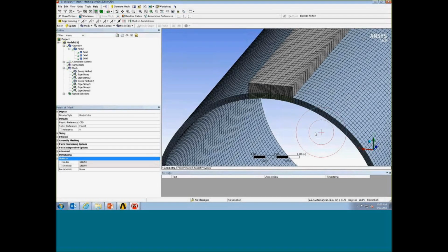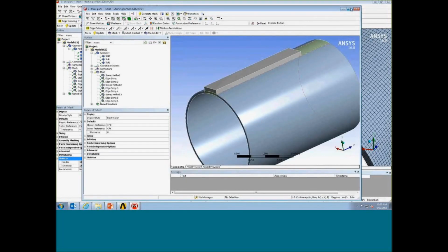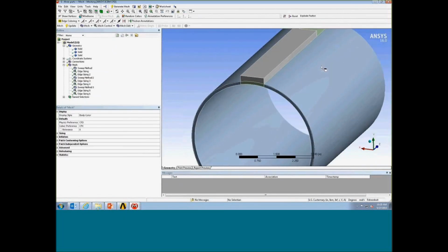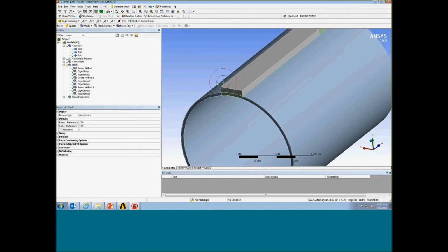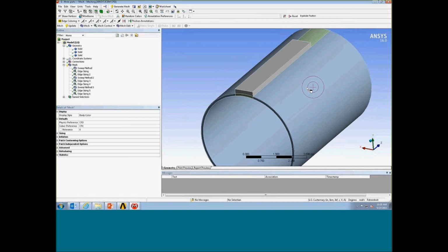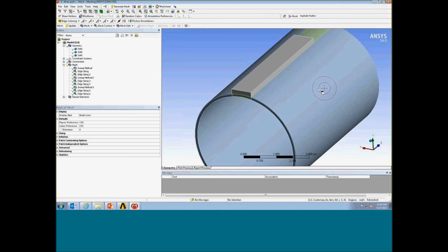And the next scenario is very similar, but instead of making them into one single part, I slice and dice the flow domain into the same three flow volumes, but they are of different parts. This is a situation when you find the conformal mesh is difficult to generate.